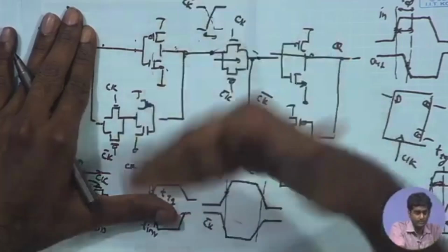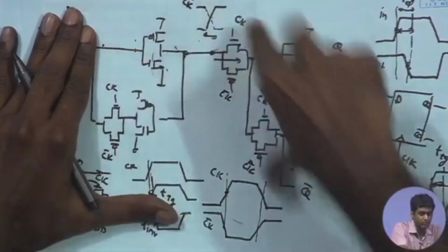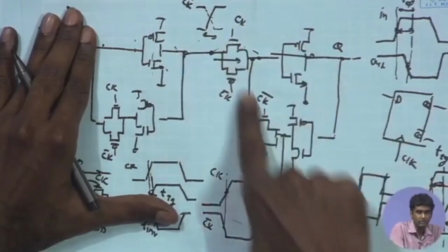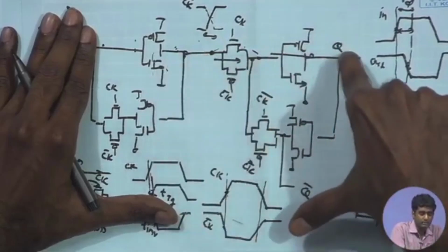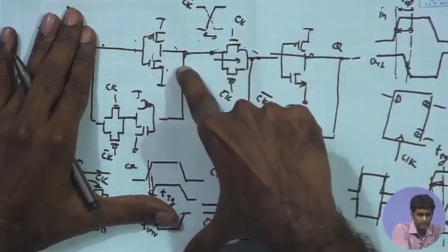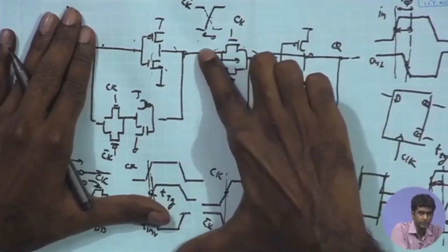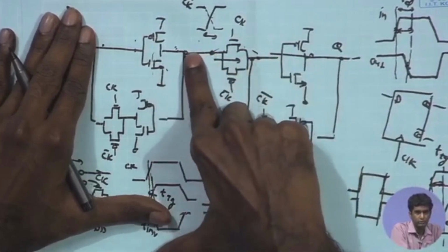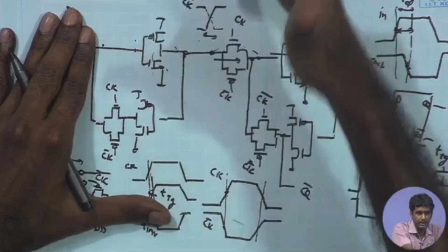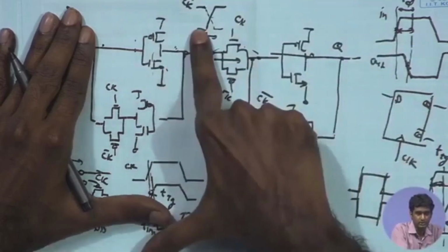What is adding more to the damage is that this overlap of the clock can further impart the influence of Q to this point. Even if you do not have the influence of Q to this point and this data has not settled, you do not know where it will end up. It can end up high or low because it is in the transition point.